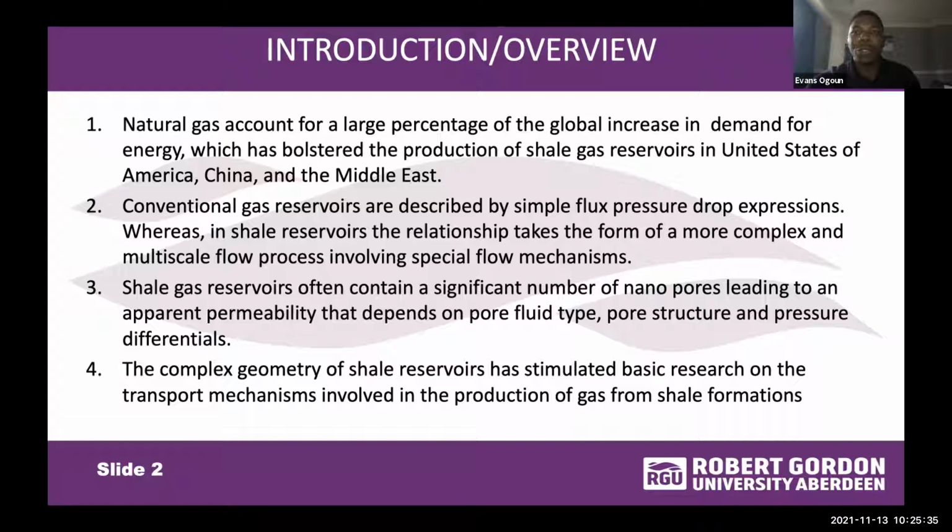In more conventional gas reservoirs, gas flow is simple, uncomplicated, and can be described by simple flux-pressure drop expressions. But in shale reservoirs, however, this relationship takes the form of a more complex and multi-scale flow process involving spatial flow mechanisms.